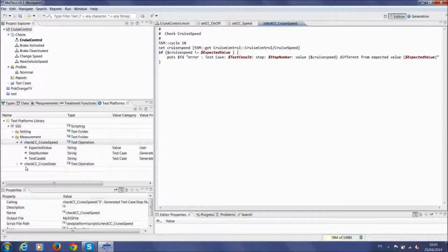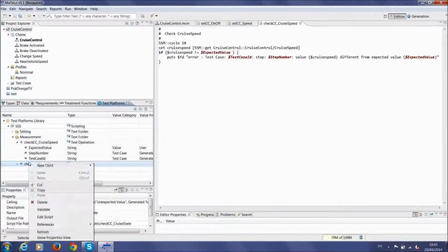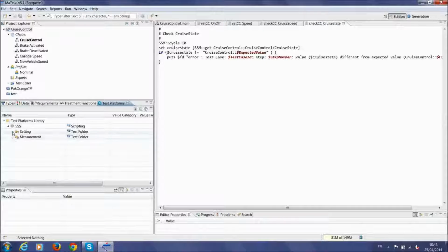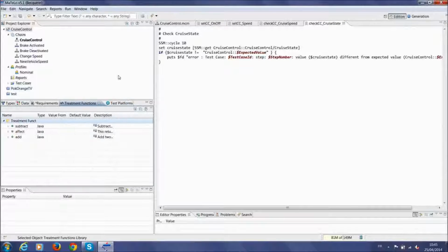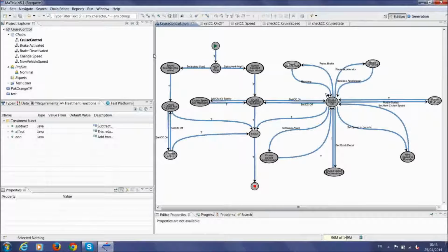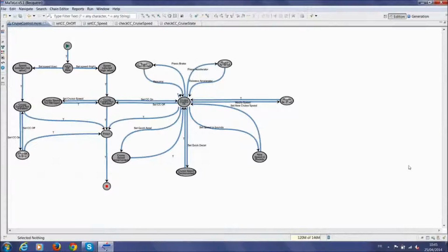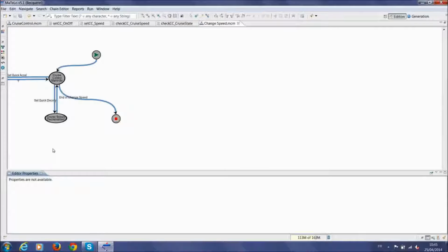This parameter appears in red in the edition field, which means that you just defined a keyword for your function. In your test model, when associating a test script function to a transition, and this parameter to a variable of the model, MaTeLo can generate your test script functions by instantiating these parameters with the default values used in the test model during the execution of the test algorithms. Keep in mind that these functions will be used by MaTeLo to create test scripts so that your system under test behaves accordingly to the simulation environment.